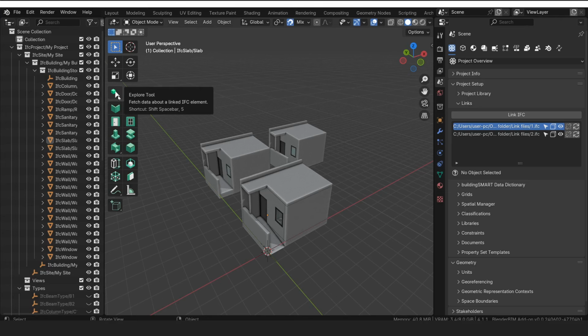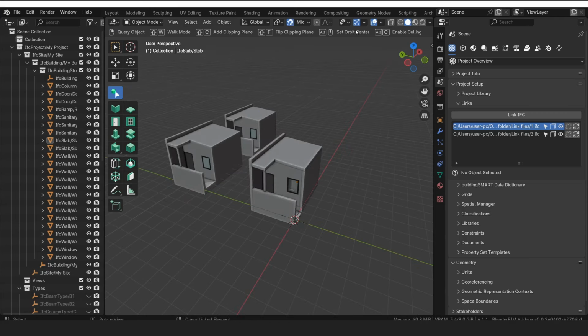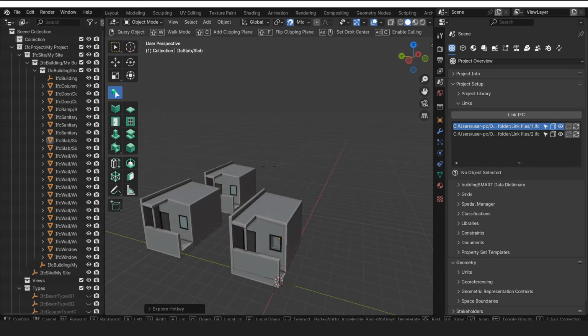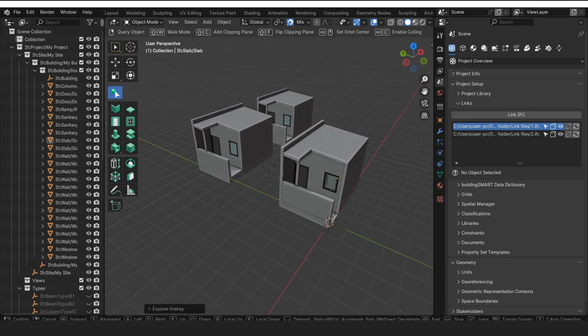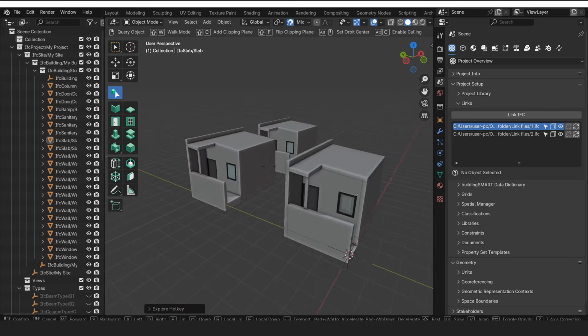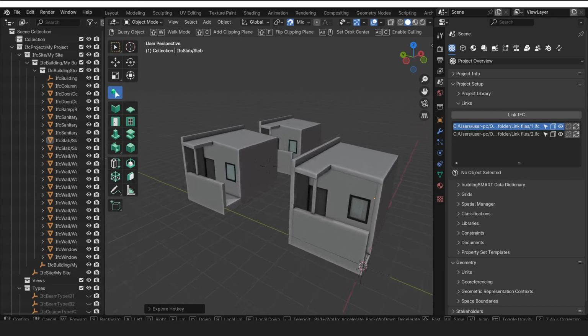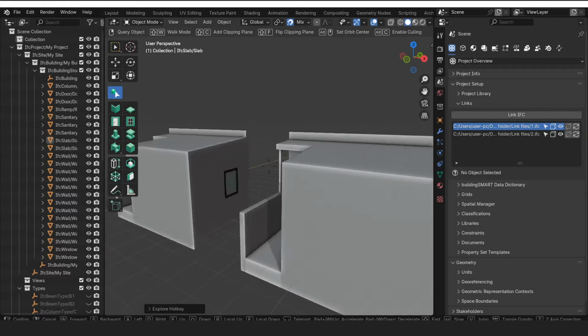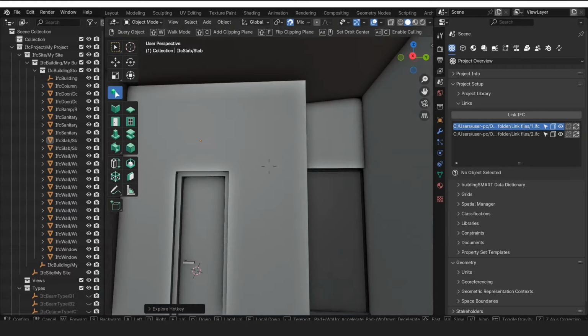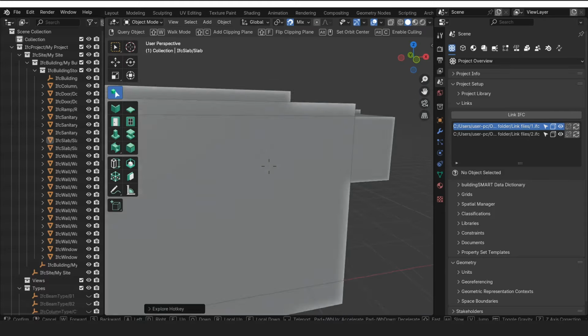Okay, so you can see on the left-hand side here, there's this new thing called the Explore tool, and inside of it, we've got a bunch of hotkeys. This first one is called walk mode, so you can just press Shift and W on your keyboard, and it will turn it into a first-person navigation mode. So you can see at the bottom, I've got confirm, cancel, backwards, walk, left, right, etc. as hotkeys. So if I press W and I press Shift, I can move forward. If I press S, I can move backwards on my keyboard. A will take me to the left, and D will take me to the right. This is a very useful navigation mode if you want to see first-person views and really inspect things from a normal person height, essentially.